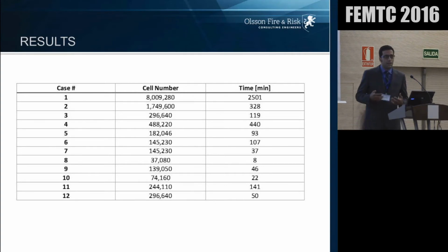LES model, using FDS, for instance, or shall we maybe pick a less accurate turbulence model like RANS or transport turbulence model or any other less accurate turbulence model? But on the other hand, although you compromise your accuracy on the model itself, it doesn't require that fine mesh you need to resolve your accurate turbulence model using LES. So you compromise your mesh with the turbulence model you are using.